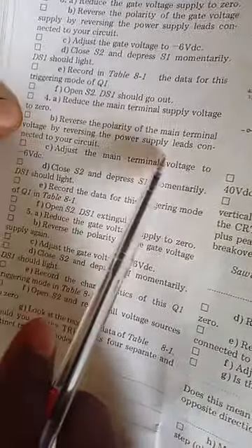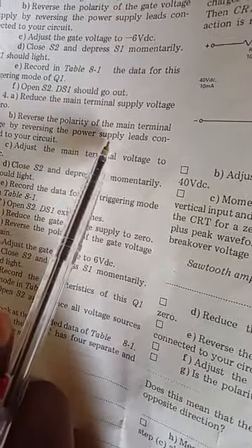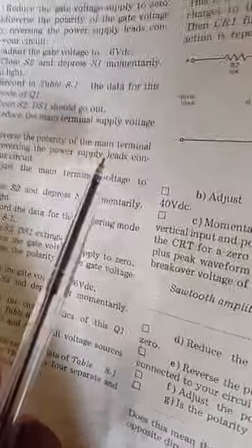So let's go to the main terminal. We are now asked to reverse the main terminal, that is the main terminal from the AC source. We want to reverse that one as well. In that case, our main terminal will be negative, and we still retain this one as negative. So that means the gate polarity will be negative. This situation is quadrant 3, so we want to implement it and see if the Triac will still operate.